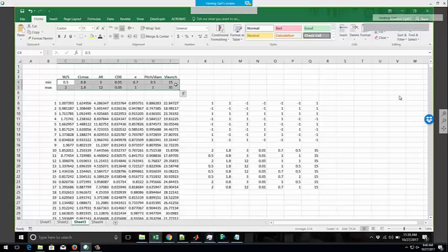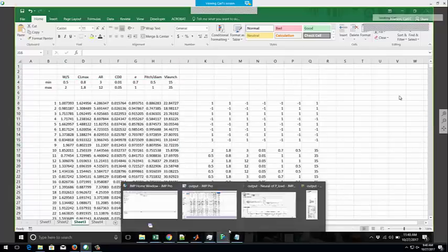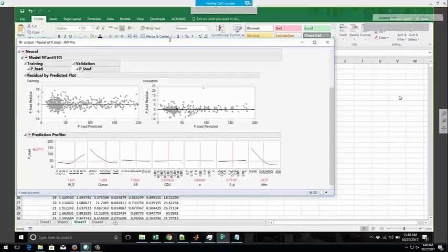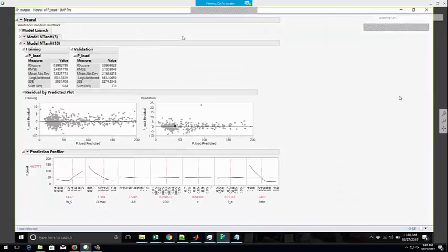So that also goes in terms of your requirements on the fuselage. You need to make sure that it can be hand launched hard, but from a requirement standpoint, if it requires some sort of epic hand launch, what are the chances that everyone launching your plane is going to give you an epic hand launch? It's probably not that high. So you may want to bias yourself a little bit lower on the wing loading side and a little higher on the power to give yourself additional margin for this hand launch, perhaps relative to some of the points that teams have been looking at so far.